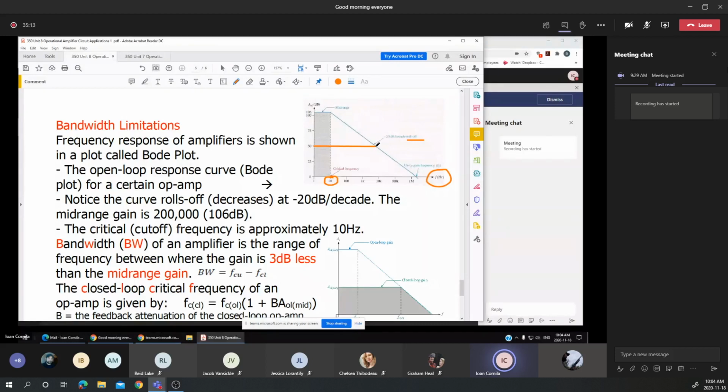You notice that if the gain of the circuit, the inverting amplifier or non-inverting amplifier, is lower, the bandwidth for the input signal increases drastically, from 10 hertz to 10 kilohertz. Suppose I can go lower than that. Because it's a constant decrease in the gain for the amplifier, I can get a much higher bandwidth for the op amp.